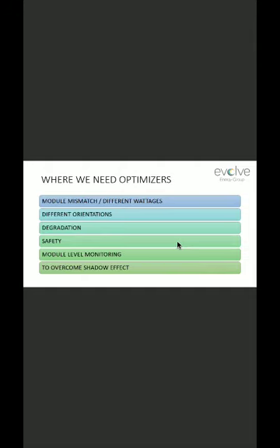So if you are going for a 100 or a 300, the optimizers will make sense at that point. You can match at different voltages, the module mismatch. Even though you are buying modules from the same factory, same lot and everything, every module has different behavior and different losses. This mismatch is lesser in the initial stages, but it will be huge later on if it is not a branded solar module.